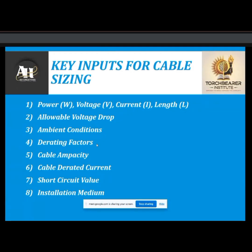They give us the ampacity of the cable based on different factors, like what is the value of the soil thermal resistivity, what is the temperature of the ground, and the depth of cable laying. On that basis, they give us the cable ampacity.